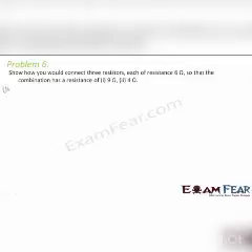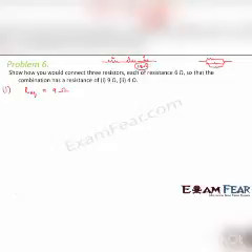So let us first look at the first part. In the first part, I want the equivalent resistance to be 9 ohms. And how many resistors do we have? We have 3 resistors, each of resistance 6 ohms. Now we are aware of 2 possible combinations. One is the 3 resistors connected in series, and the other one is the 3 resistors connected in parallel. Now if you connect the 3 resistors of 6 ohms in series, what will be your equivalent resistance? 6 plus 6 plus 6, that is 18 ohms. So that is not our desired resistance, which is 9 ohms.